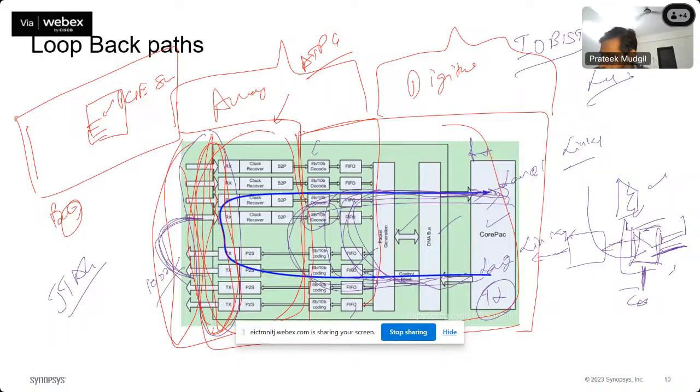So it is possible that if my TX resistance is 1000 ohm impedance, then RX is also expecting 1000 ohm impedance, right? Let us say there is a fabrication issue and both face the same issue, so the fabrication makes it 900 ohm and 900 ohm, and both of them match, and the data gets transferred. And other analog issues we can see, right? So we see that, okay, data comes like that, the data is being received properly, right?